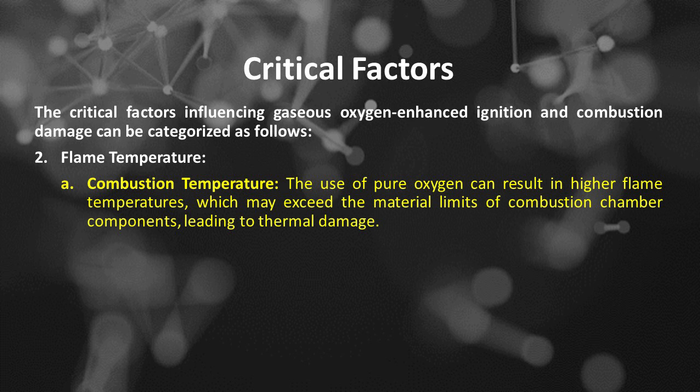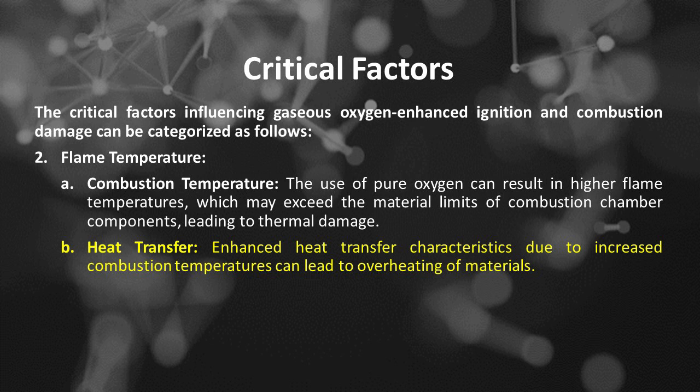The use of pure oxygen can result in higher flame temperatures, which may exceed the material limits of combustion chamber components, leading to thermal damage. B, heat transfer. Enhanced heat transfer characteristics due to increased combustion temperatures can lead to overheating of materials.